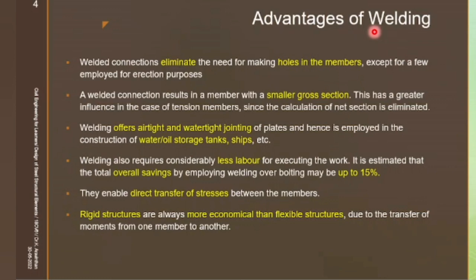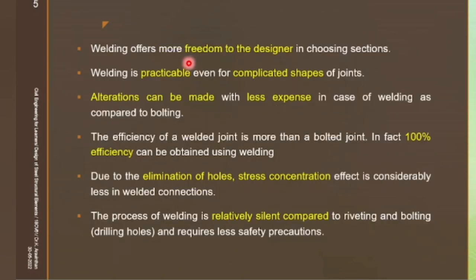So you get three reactions. What are they? Vertical, horizontal and moment. So you get three number of restrictions. So that is why weld is termed to be as rigid connection, and always rigid connection are more economical than the flexible structure. Welding offers freedom to a designer.